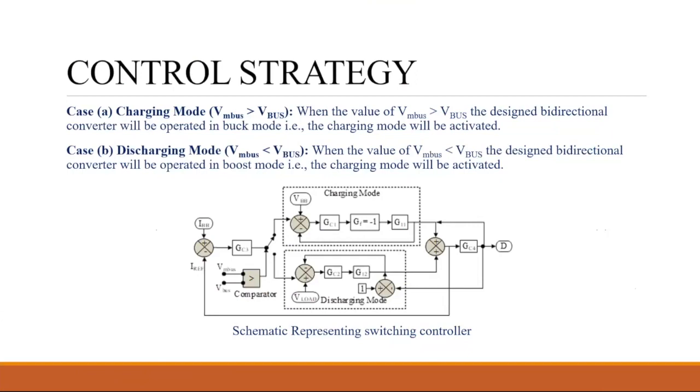Based on the reference, we are generating a control signal, and based on that control signal, we are choosing whether we have to do the charging or the discharging. And at the end, we are getting a duty cycle. Why? Because we have semiconductor switches, and we are using this duty cycle to control the switching of these MOSFETs. So that's it. That is how it's a simple control strategy.